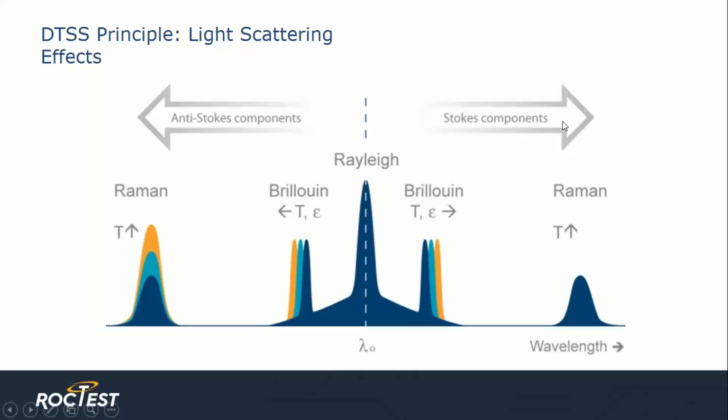The scattering process is an intrinsic property of the propagation of light in the silica material from which the sensing fiber is made. The analysis of the backscatter light consists of the combination of, first, the use of pulse light that enables the localization of the event along the fiber, and secondly, the spectral analysis of the scatter light that provides the temperature and strain information along the fiber.